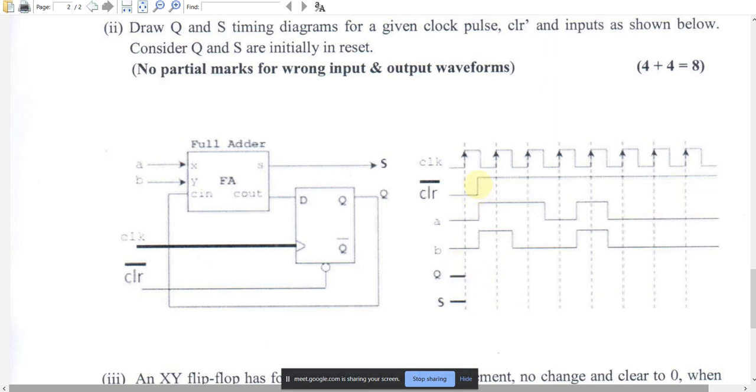So accordingly you'll have to make one more output out here, which will give you Q based on the clock. So whenever the clock is going high, you have to see if there is any carry. If there is a carry, Q will be high. If there is no carry, Q will be low. So you keep constructing this waveform out here. Is there any doubt in this circuit? Anybody? Is it clear? It only appears complex. If you just think it clearly, it is a pretty simple circuit.